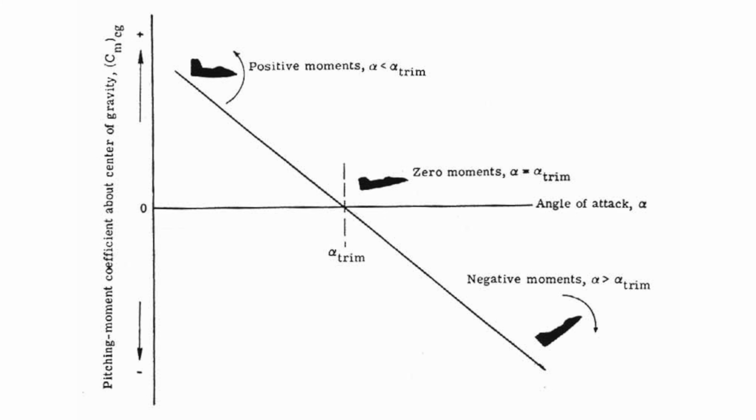On the C sub m plot, which describes the behavior of the airplane as a whole, not just the tail, this appears as C sub m decreasing as the angle of attack increases. If the angle of attack decreases instead, the opposite happens. The aerodynamics produce a nose-up pitching tendency. The airplane is pushed back towards its original condition. The farther you disturb the airplane from equilibrium, the stronger the restoring moment becomes. That's negative feedback. That's static stability.